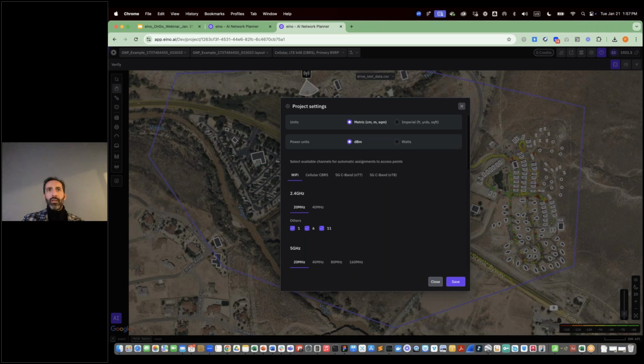And somebody asked about ducting. At the moment, our model for wiring uses a specific grid, but we are adding a feature so that you could draw your ducting and we automatically put the cables inside that ducting for you, and in that case it would calculate, and then you can make sure that you have the correct cabling there.